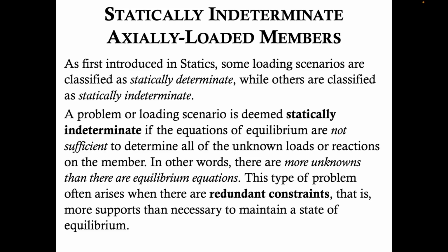A problem or loading scenario is deemed statically indeterminate if the equations of equilibrium are not sufficient to determine all of the unknown loads or reactions on the member. In other words, there are more unknowns than there are equilibrium equations.